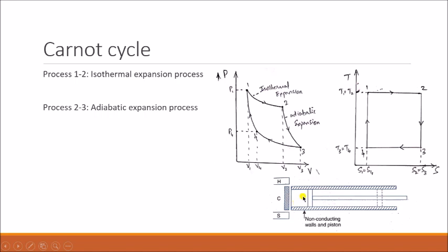So the expansion takes place due to the energy, what we call internal energy, that it had during the first process, or whatever internal energy it has absorbed during the first process. Clear, guys? Okay, so this second process we call adiabatic expansion. Expansion is taking place, but there is no heat transfer. So again, you can see here the pressure reduces further, and again the volume increases.